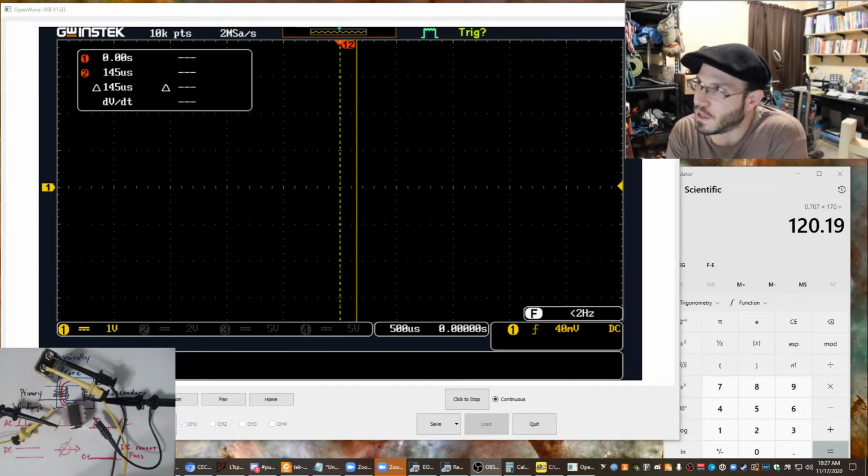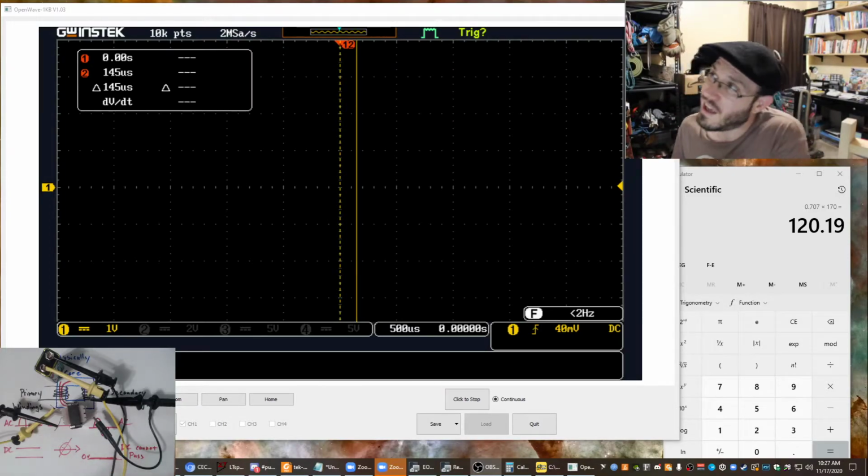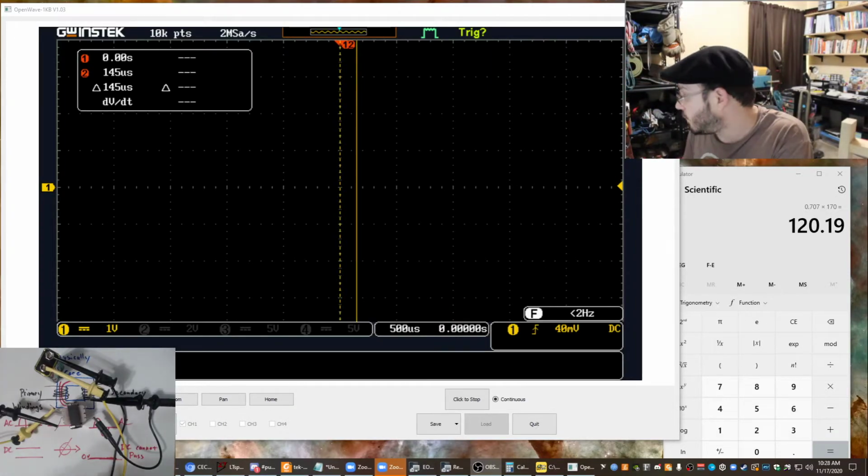So once that magnetic field builds up, if you go from 0 volts to 9 volts, then yes, when I initially attached the battery, there was a changing magnetic field, but eventually that magnetic field stopped changing. And the moment we get no change in our magnetic field, we get nothing coming out of the transformer. But inside of the transformer with AC applied to it, absolutely you are getting an alternating rotating magnetic field.